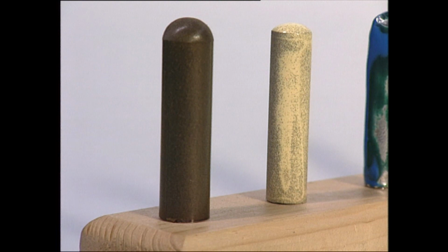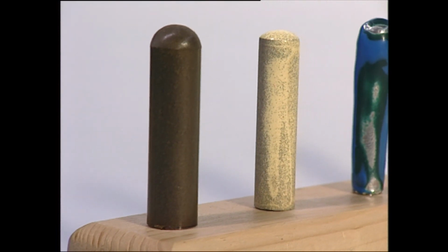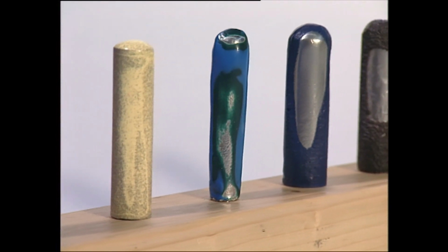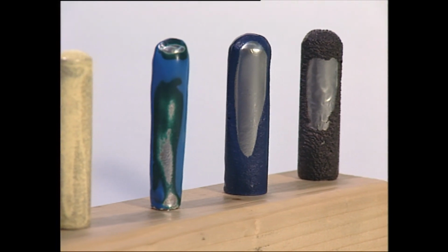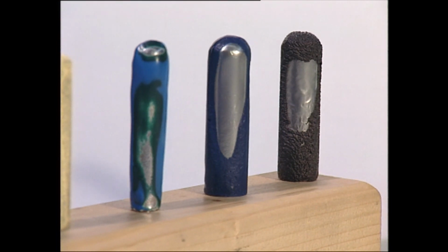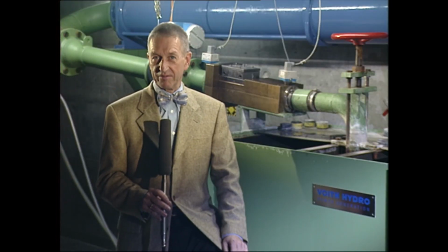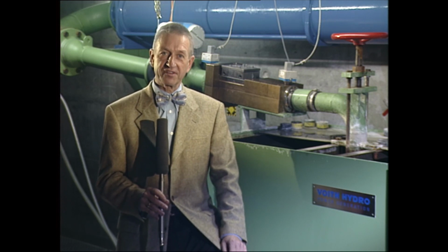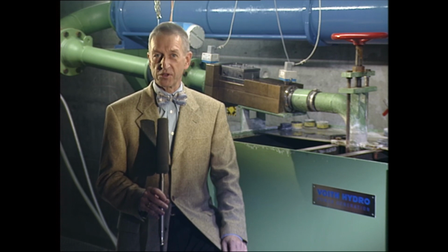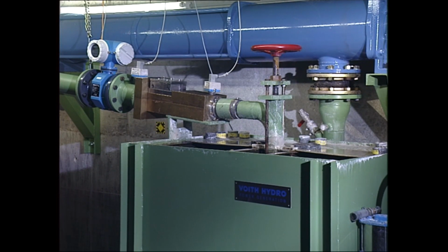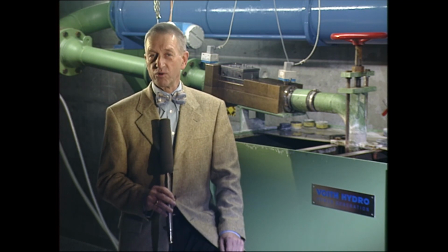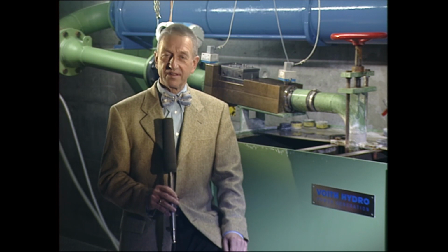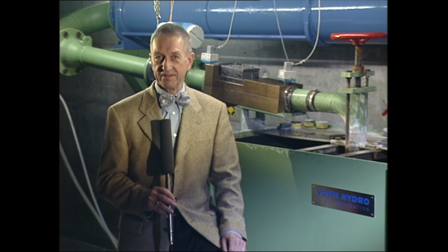Amongst the polymer coatings, there is a clear classification with superior results for high-performance polyurethane materials, in contrast to the poor results of other systems. The slurry pot test, however, shows some characteristics which make it difficult to transfer the results to real-scale hydraulic machines. This test rig provides flow conditions as close to real hydraulic conditions in practice as reasonably possible.